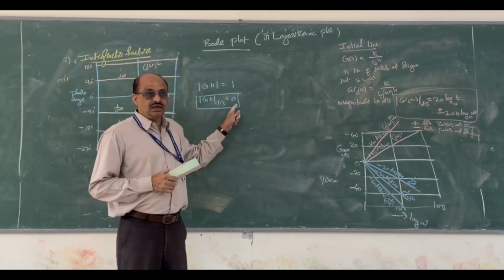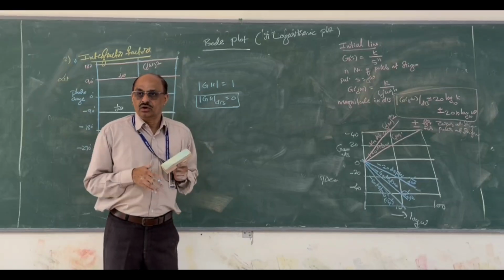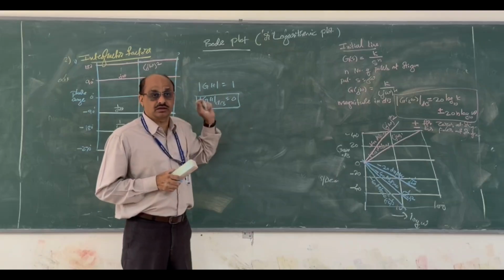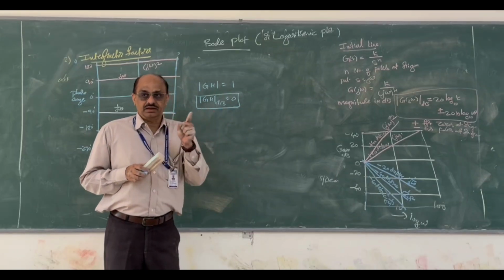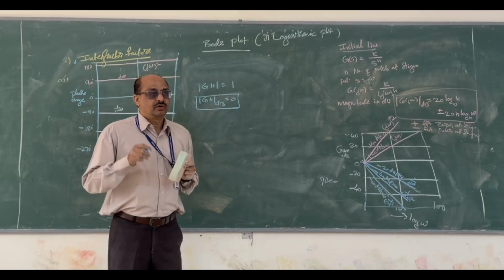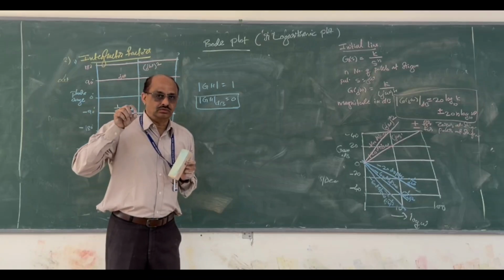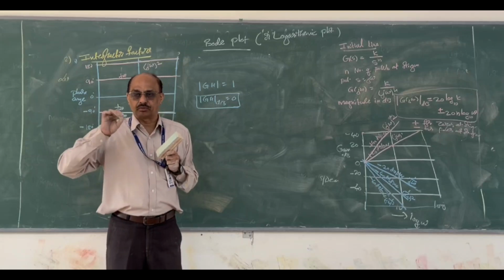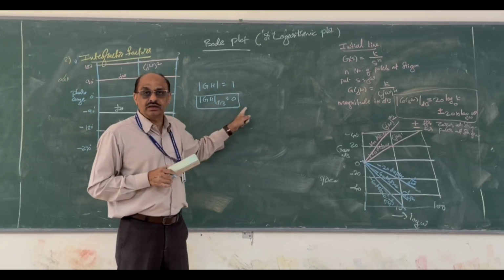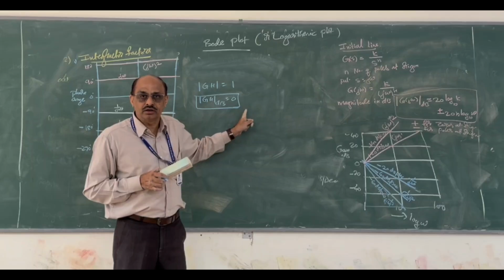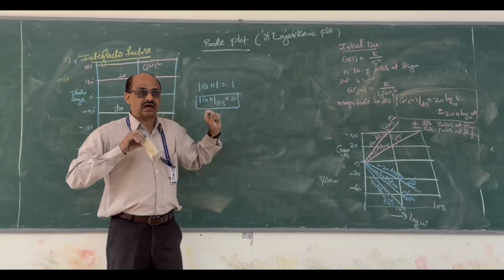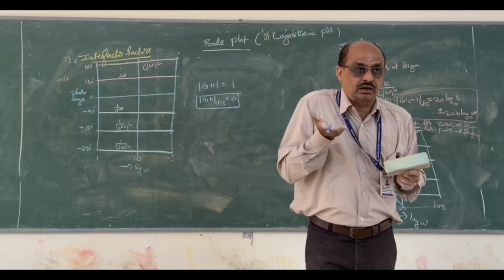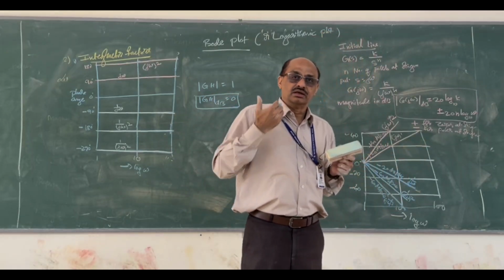So that means for a closed loop system, stability can be analyzed with respect to the 0 dB line. In the polar plot, stability is analyzed with respect to the minus 1 j0 critical point. Now the 0 dB line is called the critical point. So relative stability as well as absolute stability is now discussed with respect to the 0 dB line and minus 180 degrees in the phase angle.